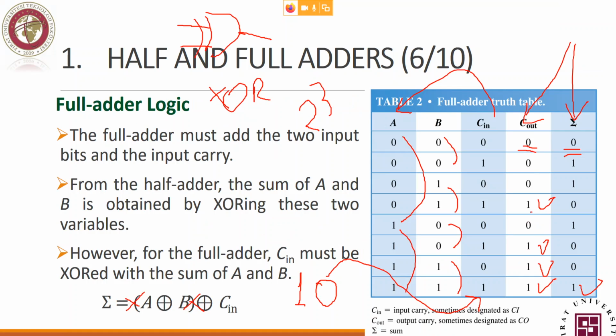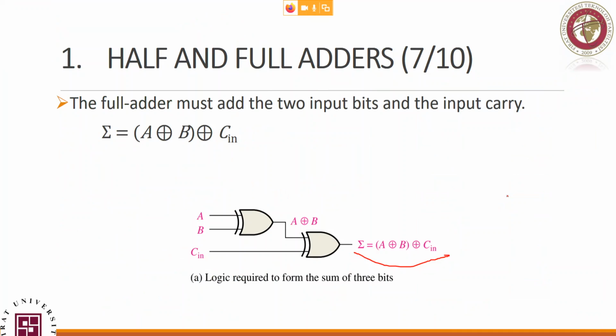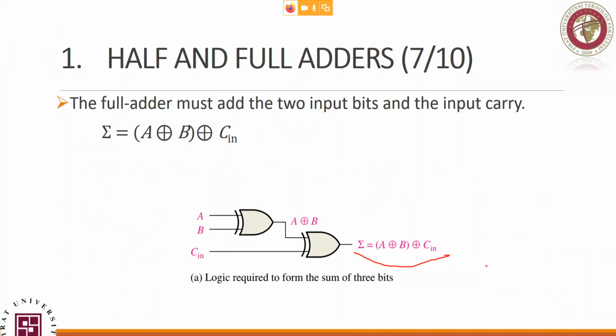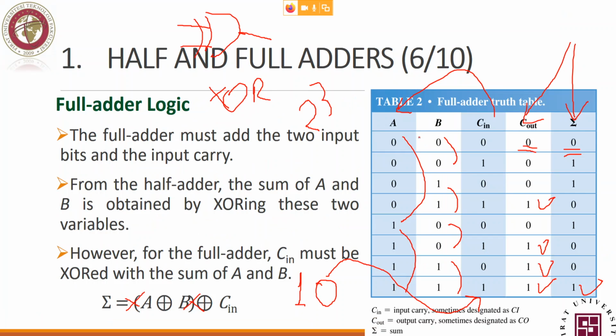You can revise it, okay? You can revise if this one is true or not, going through the truth table. So we said that we have A XOR B and Cn, or A and B. A XOR B and Cn, that's 0 here. Why? Anything and 0 is 0. A XOR B and Cn, while A XOR B is 0, anything and 0 is 0.